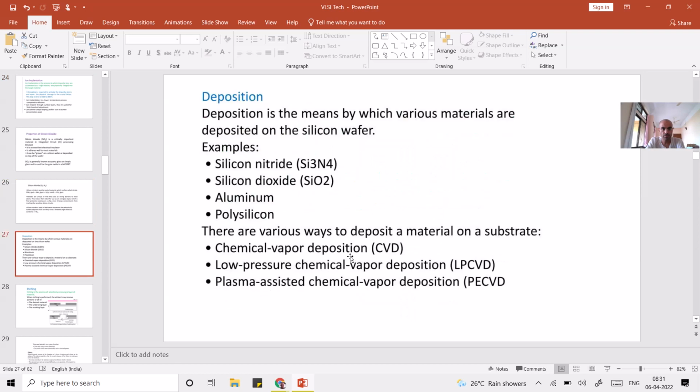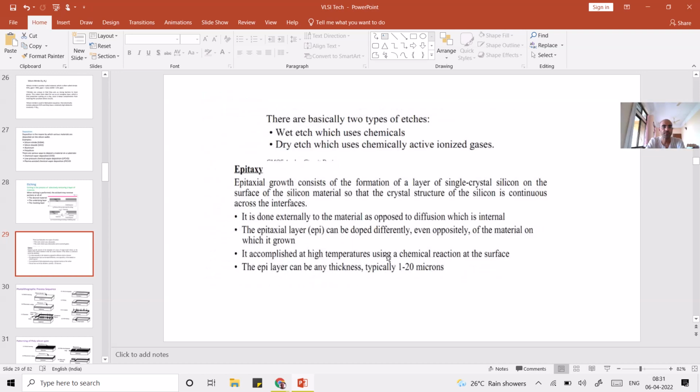So yes, these deposition methods, you use them even for depositing the epitaxial layer. An epitaxial layer is a very thin layer, though it should not be extremely thin. If your substrate is of the order of thousands of microns, let's say 10,000 microns, then your epitaxial layer will be somewhere around hundreds of microns. Not angstroms, I'm talking about microns.